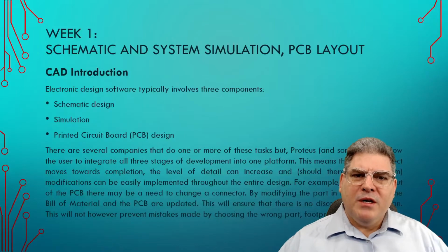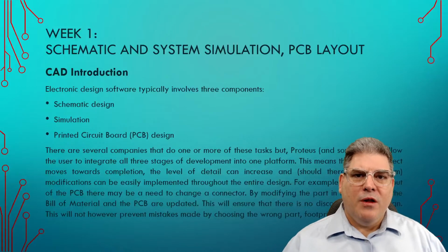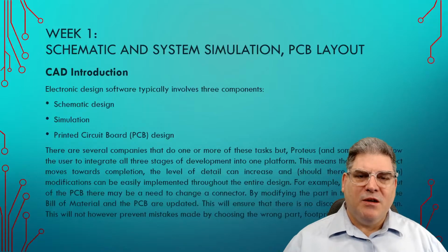It means that we can tie together our schematic, our bill of materials, and our PCB into one environment, so that when we make a change, it's seen as an update across the entire design, as opposed to needing to go into the software and change the PCB, for example, because you changed something in the schematic, and then go into another piece of software to update the bill of materials.